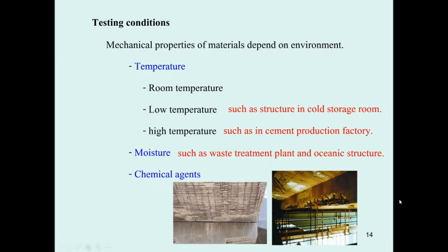So in the ocean, in shoreline structures, you have to consider this in very much detail. And also for some chemical agents such as the ones in a treatment plant, you also need to use special concrete with some specific additive to make the concrete very durable against the chemical agents.